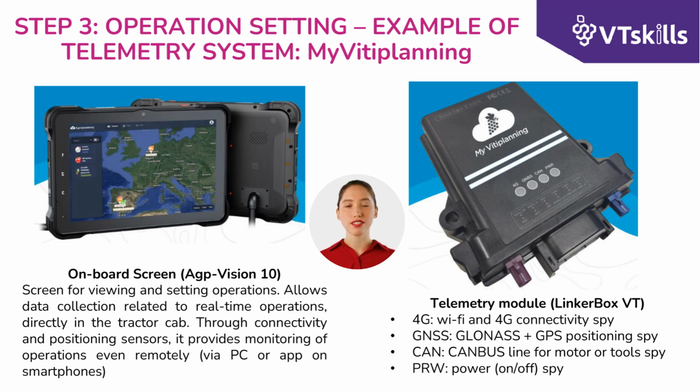This protocol, initially developed in the automotive sector, is an ISO 11783 standard widely used on agricultural machinery for the safe and standardized rapid exchange of data between control units and electronic components without complex point-to-point wiring. In the most advanced versions, the operator has a visualization, configuration, and control interface for the sprayer installed inside the tractor cab that allows complete control of the operation.